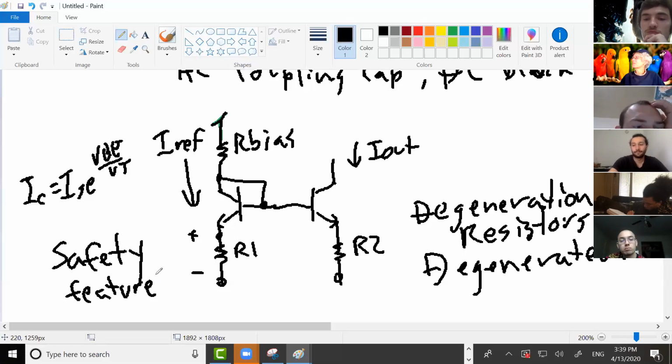But in circuits, you generally don't get anything for free. So for example, in 307, when you wanted a circuit to run faster, in other words, have a higher rise or fall time or something like that, you increase the current. But when you increase the current, what bad thing happened? More power dissipation. So that was a trade-off between speed and power.